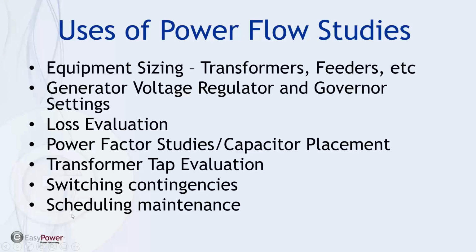You might say, well, I do that with thermography now. One of the issues with thermography is if you're not taking the image at the maximum load that the equipment's designed for or usually runs at, you may not get an image that indicates there's a problem, whereas load trending or loss trending that you could track in PowerFlow would at least give you an idea when to take the snapshot of the thermal image.